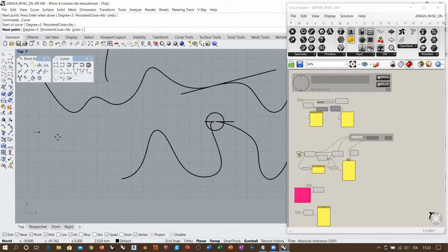I'm talking about an organic shape like this one that suddenly has a straight behavior or aspect, and then goes back to an organic shape, all in one single line, not like drawing a NURBS curve and then drawing a straight line with a polyline and then another NURBS curve segment and then joining all together. I want to do this only with one single NURBS curve command execution.